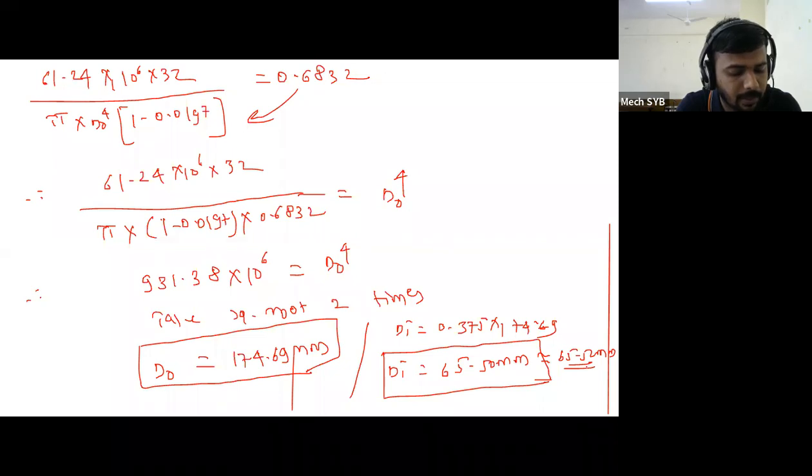Yes, the value from the angle of twist is greater, sometimes, maximum times, if you do the calculations based on the angle of twist. Now here the angle of twist is 1.4 degree. For the previous problem, the angle of twist value is 2 degree. There is a variation in the diameters. And now if you see both the problems, in both problems the angle of twist values have come out as the maximum. If your angle of twist is maximum, then based on that particular theta value, your answers will vary.